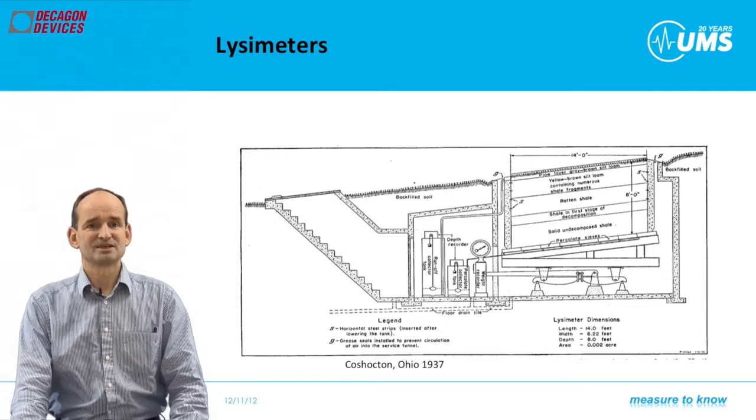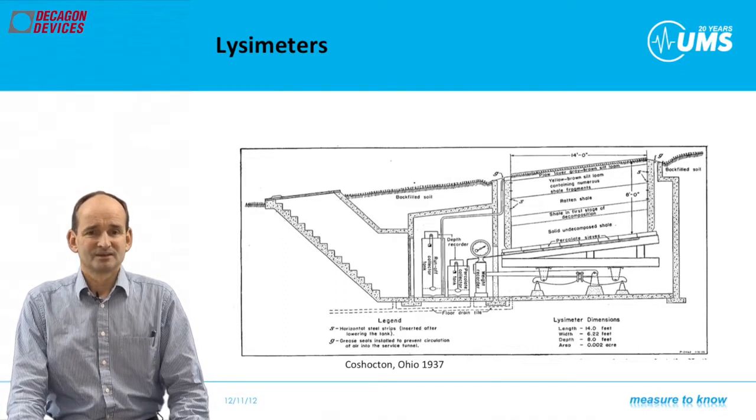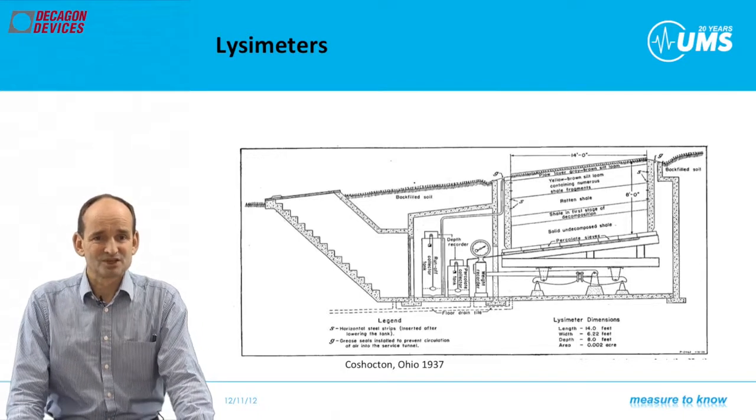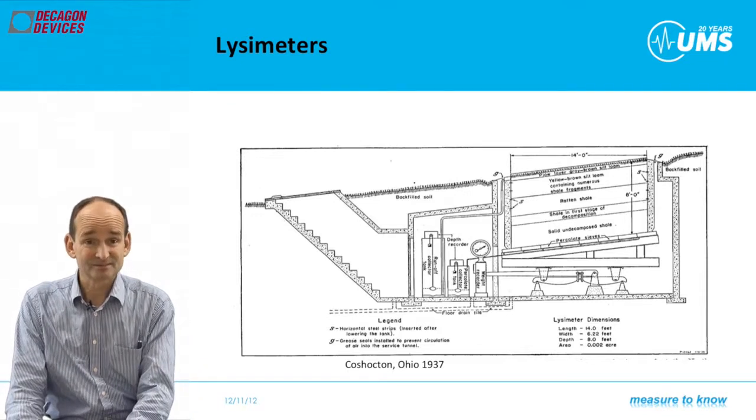This slope lysimeter does not take into account lateral fluxes, which may be dominant at slopes, but it measures the runoff in a separate vessel, which is important for slope studies. It has a defined lower boundary, which is here 0. Water will flow to the drainage barrel without any potential. This point will be part of the following slides.